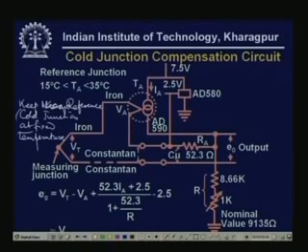So that's cumbersome. Therefore, what people try is this: suppose you keep the reference junction in the open, so the temperature in the ambient is going to vary, and that will cause some error. So what you should do is compensate for the ambient temperature variation using electronics, by measuring the ambient temperature variation. That's the smart way to do things, which is also much easier.